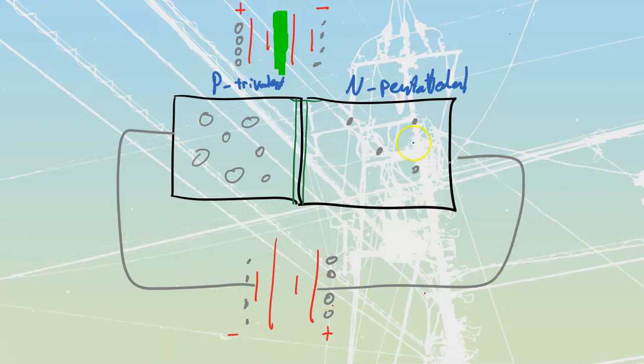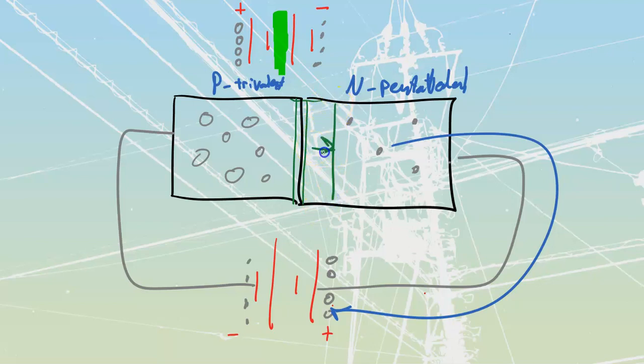Well, we see that all of these electrons, which we have an excess of, are going to see holes. And what happens when we get electrons and holes is that those electrons are going to flow out of here to fill those holes. And that depletion region, which was small in the beginning, in the area where we had balanced this down to 4 valence electrons, is now going to start to grow.